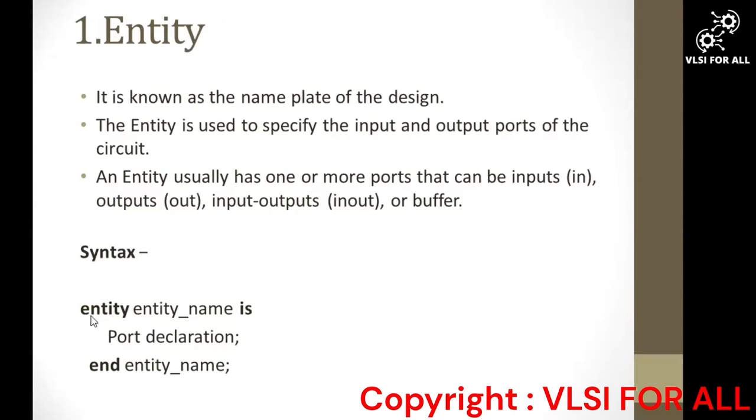First we will use the word entity. After that we will give the entity name. It can be any name you want to give. And then after that, is. After that, port declaration. What is port declaration, we will see in further slides. In this we have to declare the input and output ports. And after that, we have to end this entity with the end statement, followed by its name.